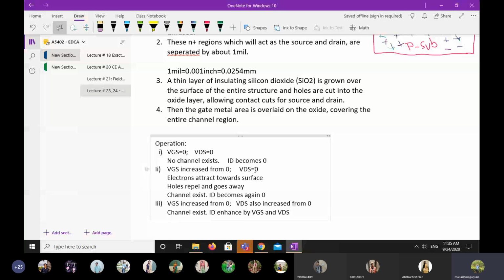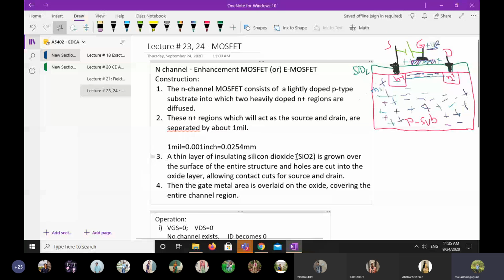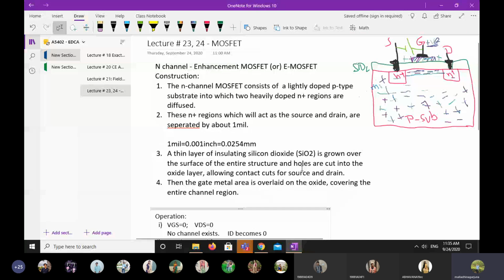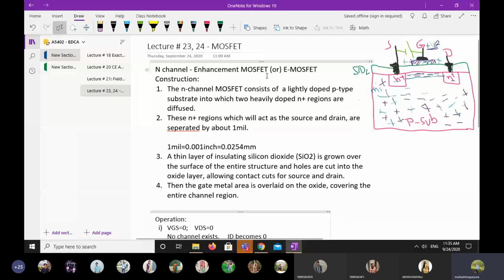So that's enough. They need not prepare or add anything. The only thing to keep in mind is that the source should repel, so that it emits the charge carriers, and the drain has to collect the charge carriers. Okay, in this n channel enhancement MOSFET, the gate is always positive. You are not supposed to apply a negative voltage here.